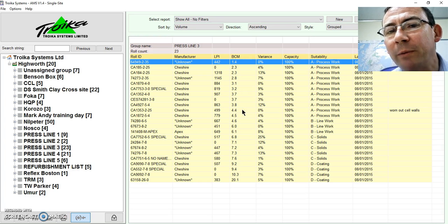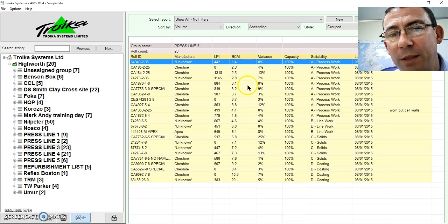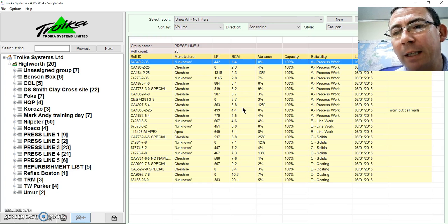However, the real reason that gives them a stronger colour is that the alternate roll, and we can see here, there's two rolls here, same specifications, but I've got a variance in the volumes. And therefore, it'll deposit less ink, and I get a weaker colour.